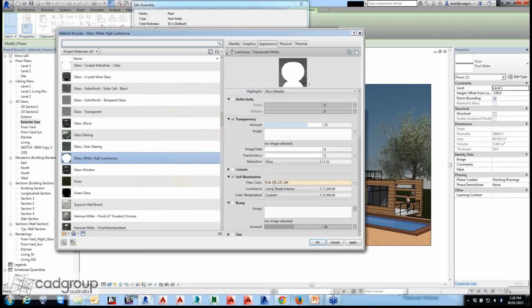So if it is a little bit of halogen lights, you might want to change a little bit of light filters, and you can set the luminance value. Now, we've got a preset of values here, whether you can say to use for the different purposes of the self-illumination. So if you've got an LED panel or LED screen, we can see there are a couple of different presets that have different values. So if it is just a simple dim glow, we can use a value of 10. You've got an LED panel which uses like 100, etc.